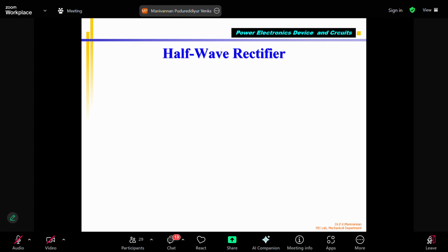That is what is supplied to any appliances, which can be three-phase motors, single-phase bulb, TV, fridge, all those things which operate on AC voltage. They will receive 220 volts or 440 volts in India. Correct? If you go to US, it is 110 volts. Phase to phase, it will be 220 volts instead of 440, that is what it is in US.